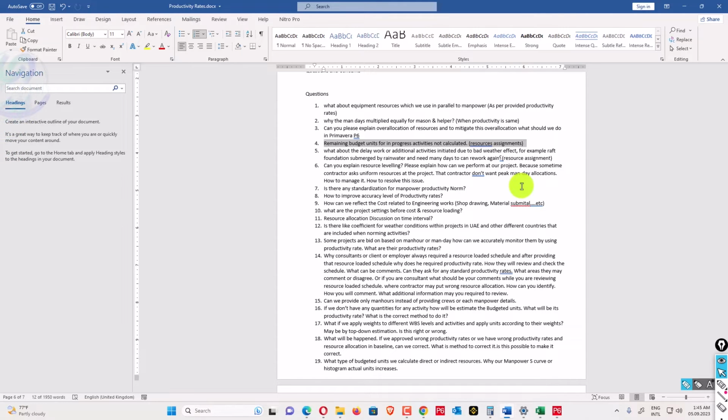They will not say which are working days and which are non-working days. The client does not have any concern with your calendar even. So the client will give you only 3 years, like a 1095 days project. You just add that to your start date, and your finish date will appear. You have to plan the complete project within that.